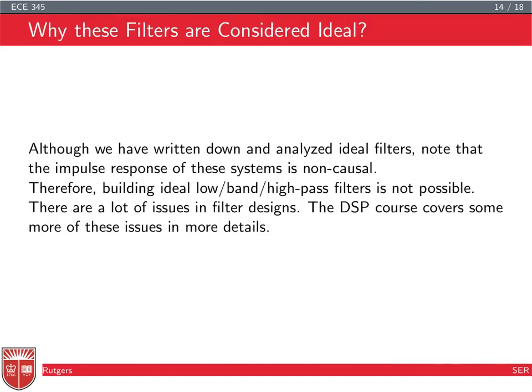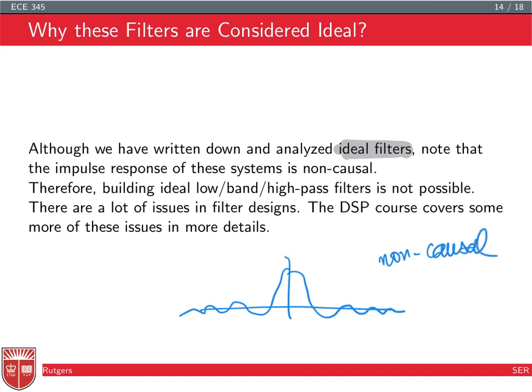We have referred to these filters as ideal filters. The reason is that these LTI systems are non-causal. If you look at the sinc function, for example, even if you give an input at t equal to 0, you're going to get an output for t less than 0. So these systems are non-causal, and therefore we cannot realize them in the real world. You cannot have an output before the input.